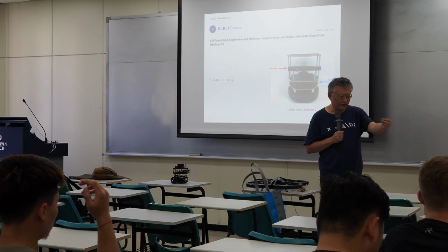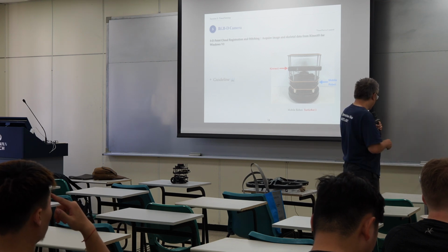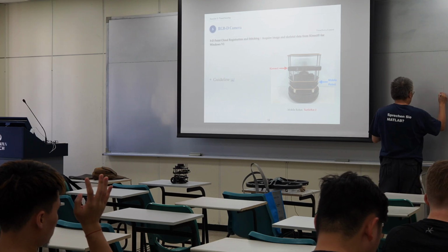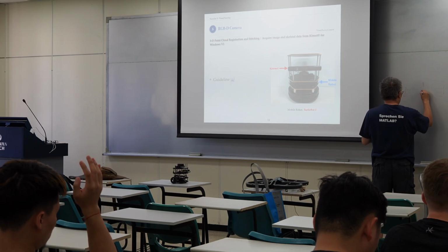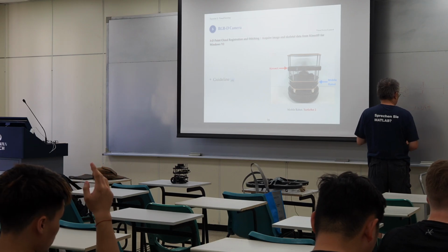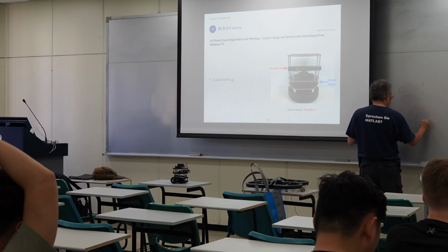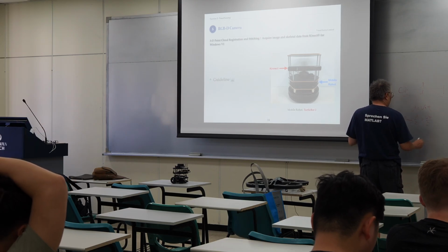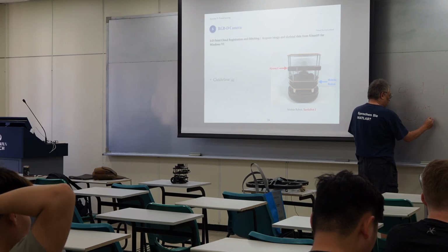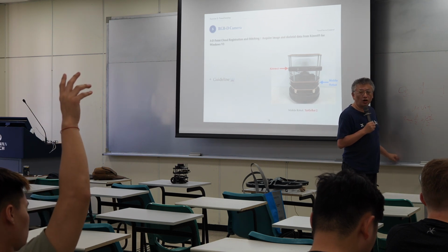For example, a laser rangefinder, time of flight. You shoot a light and measure the distance. With the laser rangefinder you shoot into the obstacle and it bounces back. So D equals velocity times the time t. So the range will be d over 2, that is vt over 2. You can measure the speed, and you just measure the time divided by 2 to get the range. That is the principle of a laser rangefinder or a sonar.